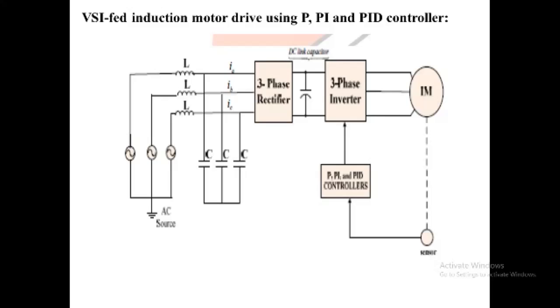The basic action involved in adjustable speed control of an induction motor is to apply a variable voltage magnitude and variable frequency to the motor so as to obtain variable speed of operation. Both the VSI and CSI are used in adjustable speed drives.